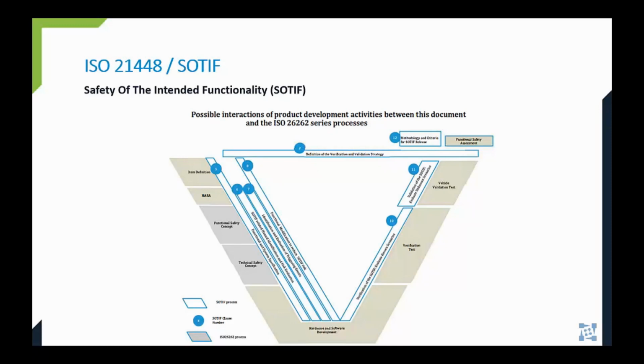Functional and situational awareness is critical to safety, especially due to the rise of complexity in all of these connected ADAS systems, with many sensors, including the use of artificial intelligence. So SOTIF takes into consideration sensors' limitations, decision algorithms, and intentional or unintentional misuses. It looks at the existing intended functionality and helps analyze and prevent the misuse of that functionality where it creates an unsafe scenario. Test cases will need to be implemented to address these unthought-of situations that are flushed out.